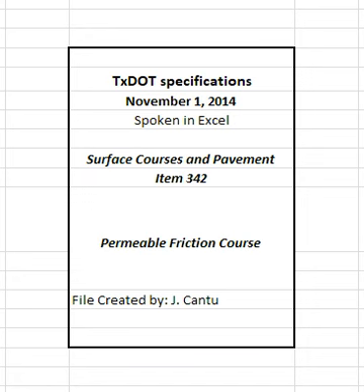4.4.2.1.5 Supplying aggregates. Provide approximately 40 pounds of each aggregate stockpile unless otherwise directed. 4.4.2.1.6 Supplying asphalt. Provide at least 1 gal of the asphalt material and sufficient quantities of any additives proposed for use.